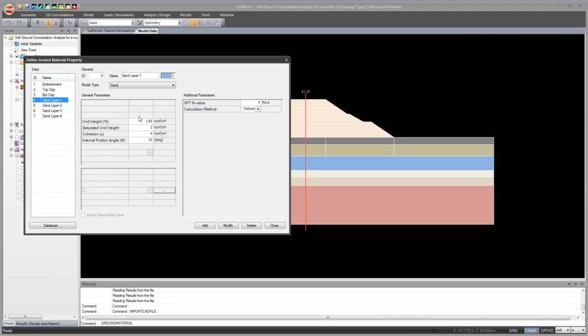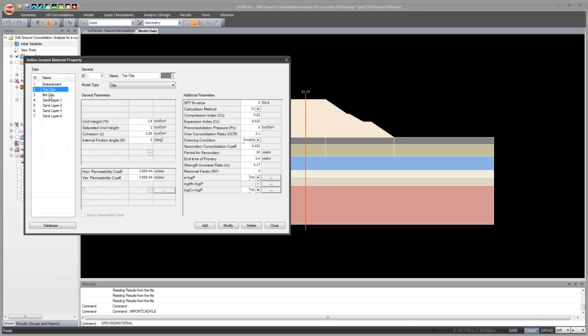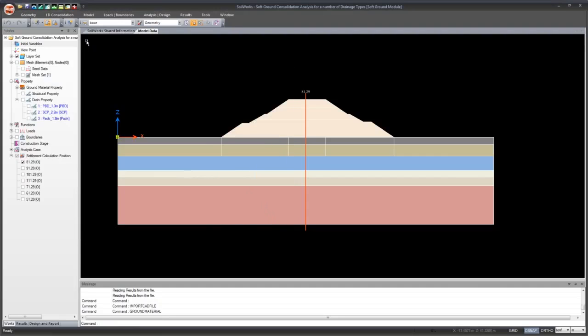That's because with sand you don't really need to worry about any sort of settlement or consolidation. All the settlement is just immediate when it comes to sand. So your primary focus really needs to be with getting these material properties correct. So anyway, once you have these material properties input into the program, what you need to do next is